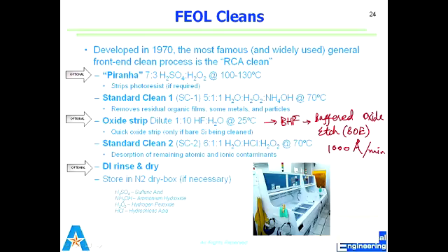There are different ways we do rinse. We'll talk about that next time. Generally, the simple one is a water rinse, you open it up. Then there's something called a cascade, where you have a sort of river of 3 compartments. The first one is filled with DI water, overflows into the lower one, and overflows into the third one, which is lowest in height, right?